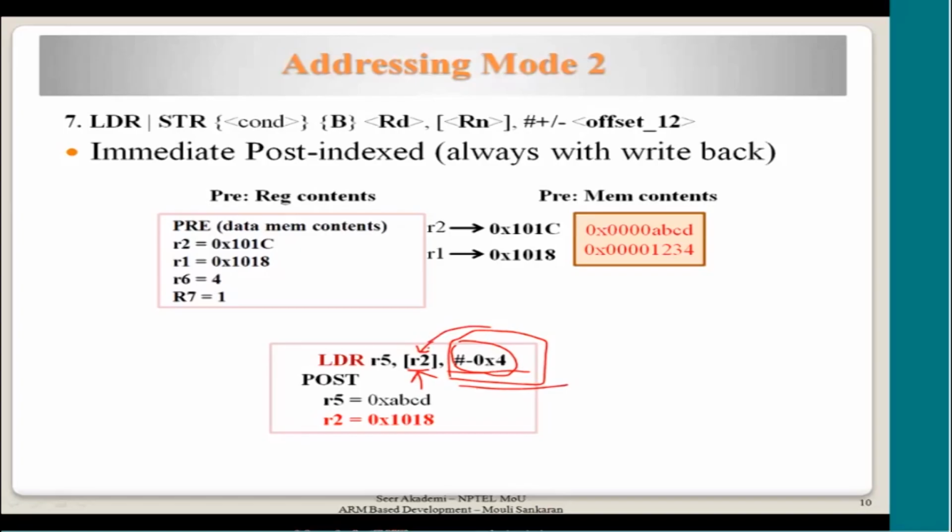That is why the ARM designers are using it internally for some other purpose. That if you are doing this, in post index I will always modify R2. So there is no separate symbol for this, and I don't treat post index differently. Always I will update the base register if it is a post index. Now post index, how will it know? It will know that if the constant or a shift operation is outside the square bracket. So it is very easy for it to encode the instruction accordingly. I hope this is clear to you.